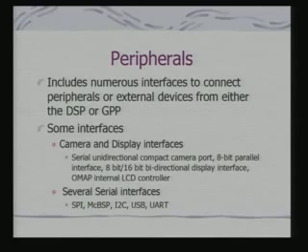It provides camera and display interfaces, because if I am targeting these kinds of embedded portable terminals, then they will typically have a camera connected to them, and so the camera interface forms an integral component of this SoC. It has basically 2 camera interfaces, a serial unidirectional one called the compact camera port, as well as an 8-bit parallel interface.